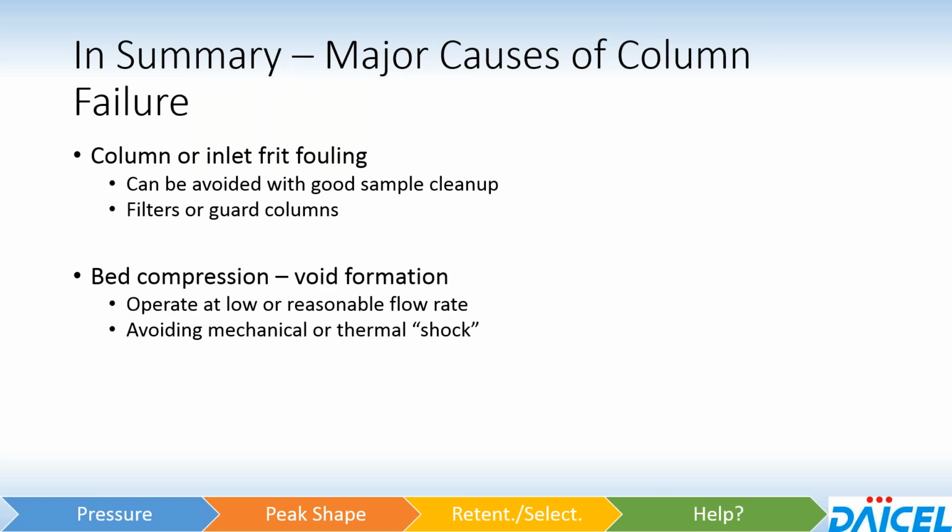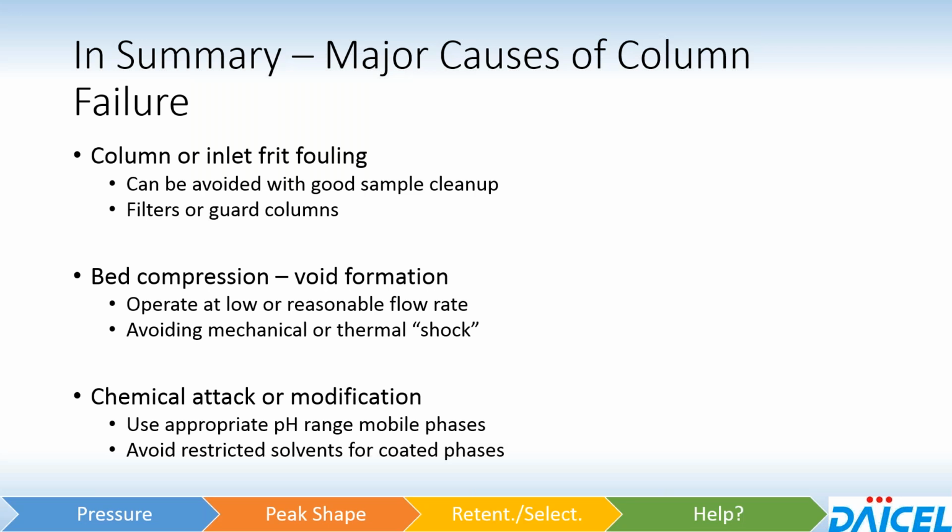Bed compression or void formation. So making sure that you are operating at low or at least reasonable flow rates as kind of outlined in the instruction manuals, and avoiding things like mechanical or thermal shock. And then lastly, chemical attack or modifications, whether it be memory effect or column history, or chemical attack as a result of using an inappropriate pH range or the using of the restricted solvents on the coated phases.